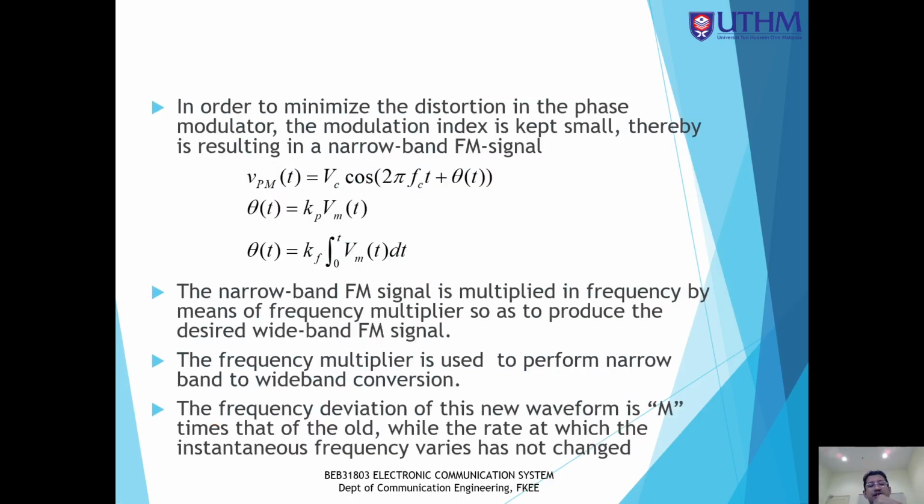What does it mean by integral? It means that theta t is the integral of theta prime t dt. This produces narrowband FM. If we want to make it wideband FM, we need to multiply the frequency with a frequency multiplier.